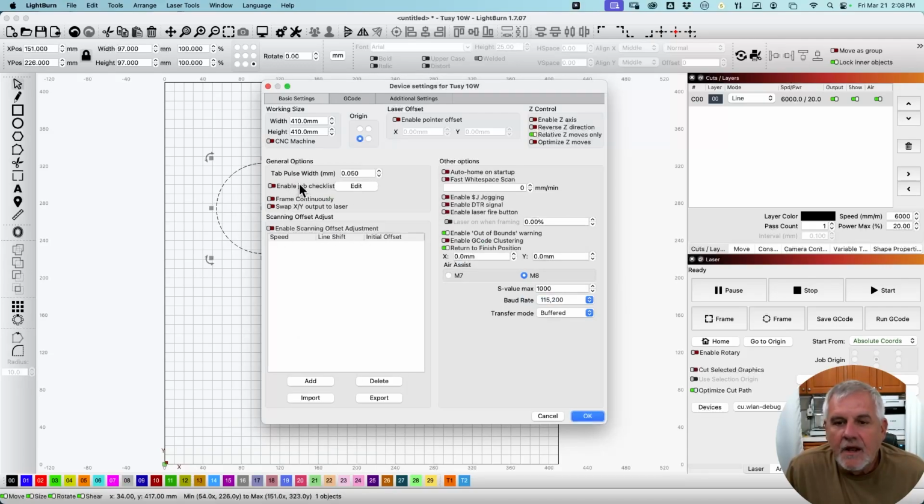So, one thing I missed up here is CNC machine. If you're working with a CNC machine that you just have a laser module added onto, sometimes you have to enable that setting for it to work properly. And what it says here, it says enable this setting if your machine has a rear right origin and uses a negative coordinate system. So that's going to be very limited use cases on that, but I just wanted to bring it up because it is there.